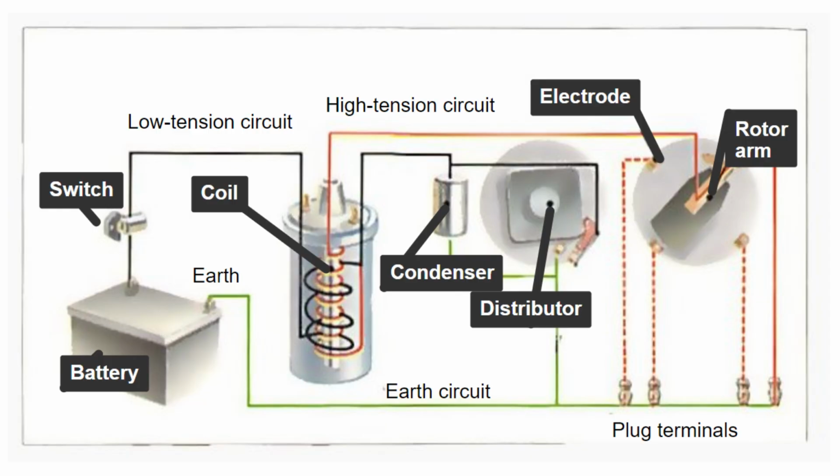Electronic ignition systems. Modern electronic ignition systems operate on the same principle, but some depend on charging a capacitor to around 400 volts rather than charging the inductance of the coil. The timing of the switching of the transistor should be matched with the position of the cylinder piston so that the spark ignites the air-fuel mixture to obtain the most angular momentum possible.